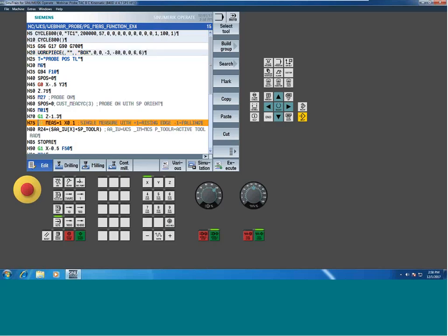So this is the meat right here. I'm telling it measure equals 1, so that's probe number 1. Since it's a positive value, I'm looking for the rising edge. Now, if you don't know rising or falling and they can't tell you, and you pick the wrong one, the machine won't move, because it'll immediately think it kicked. So that's your trigger. And you can do this in MDI. You can type in measure equals -1 and tell it to go to X such and such.